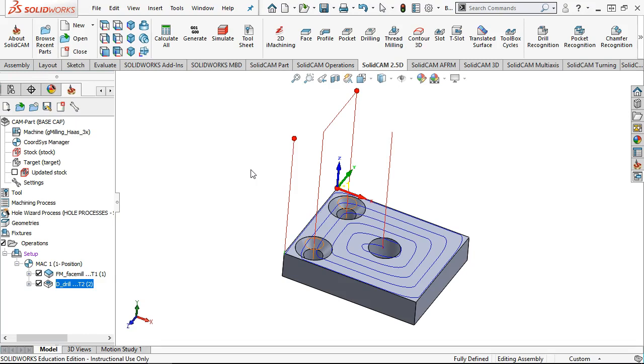So the assignment is to go through the drawing and apply the dimensions, the GD&T, and then go back to the parts like we did early on in this one, do the DIM expert and see what the software found that was different than what we created going through the process.